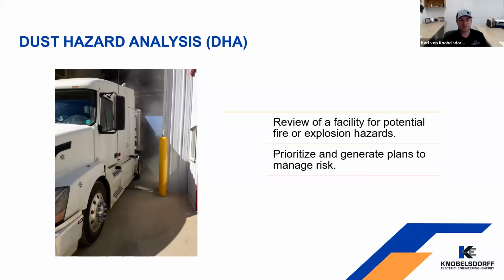A lot of times this includes adding dust collection equipment, adding explosion isolation equipment, maybe some explosion venting, and usually it's a lot of hazard monitoring installations. So finding indoor bucket elevators that don't have any alignment, speed, or bearing sensors on them, belt conveyors with no hazard monitoring, and getting those things put in place to keep you from having an ignition source cause an explosion.